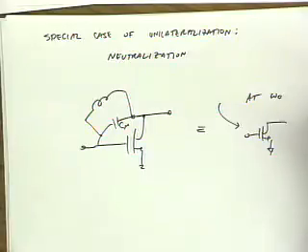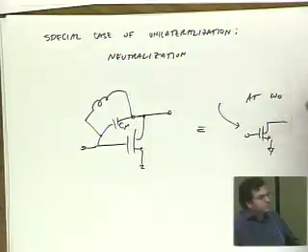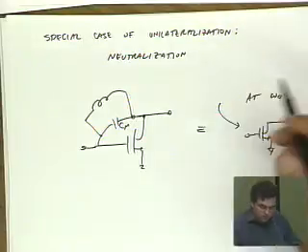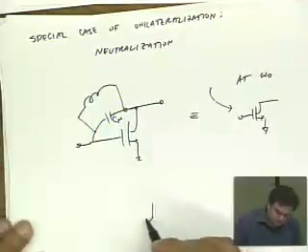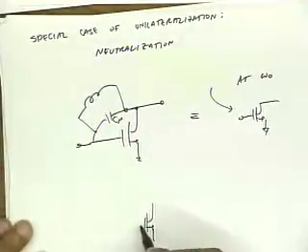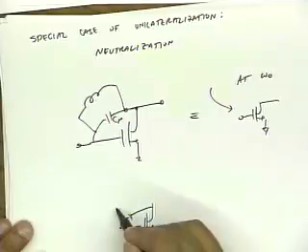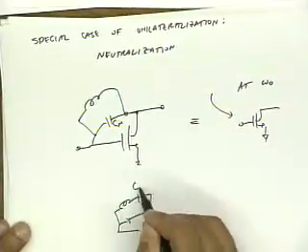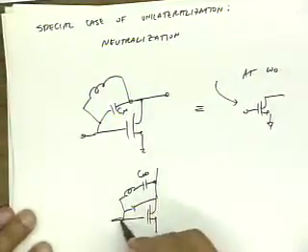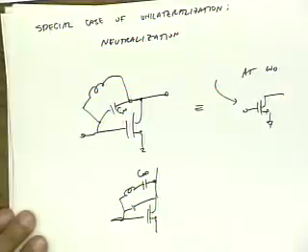And yes, there's a question? With biasing? Sure, this is an AC schematic, so the way you would do it in reality is you'd use a big capacitor here. Okay? So if I unilateralize my device, or in this case neutralize, which is easier to say than unilateralize, if I neutralize my device, then I actually do end up getting more gain out of it.